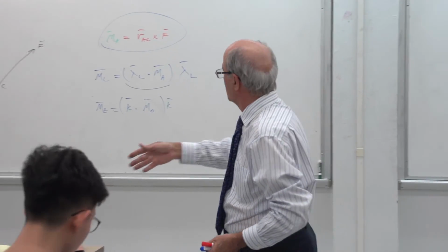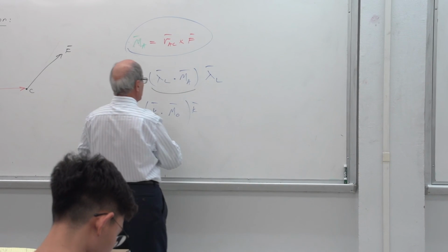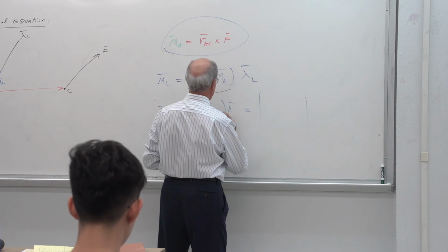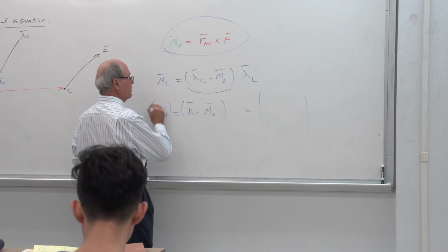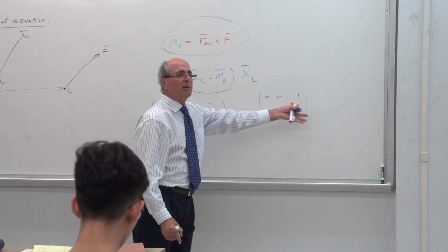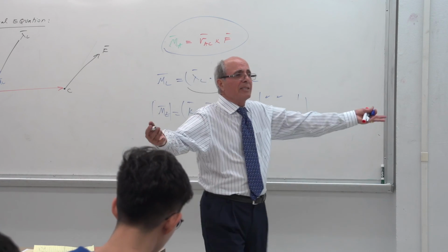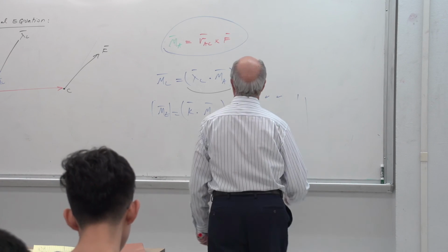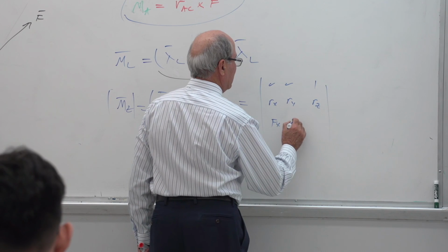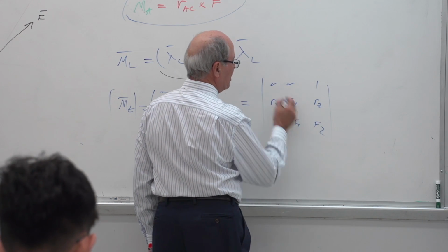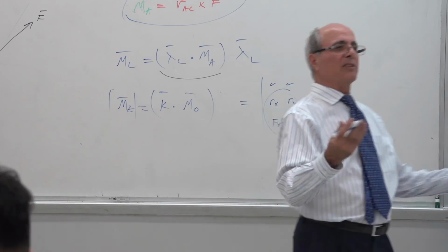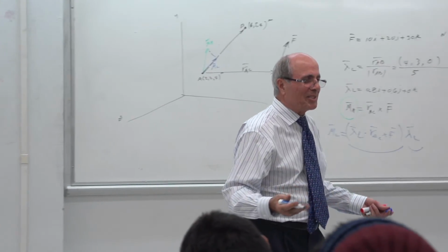Everybody understand that? Because if you check this, remember, because this is the dot product, you will see what happened here. I'm only using the magnitude. It becomes 0, 0, and 1, notice everything becomes 0 except the k direction. I already have the k. Everybody understand what I'm saying? This becomes equal to rx, ry, rz, then fx, fy, fz. Notice 0, 0, you only get 1 times that. Is that correct? And that is the moment about the z-axis anyway.